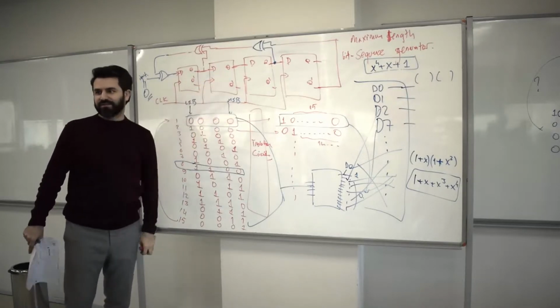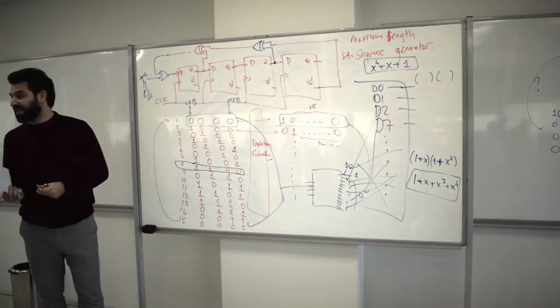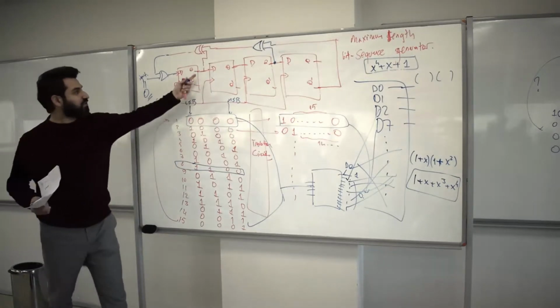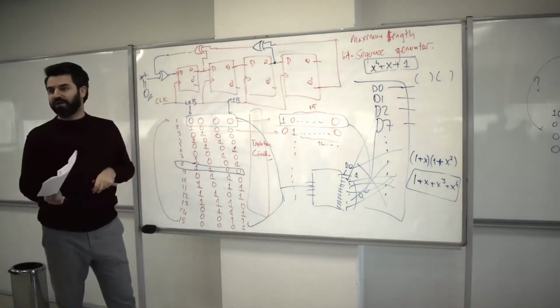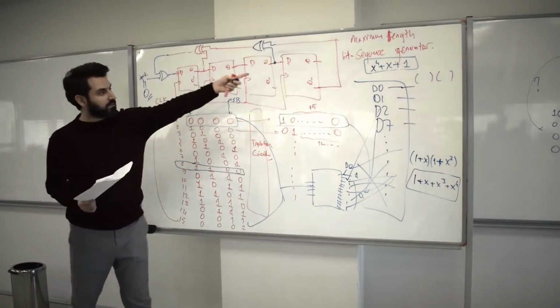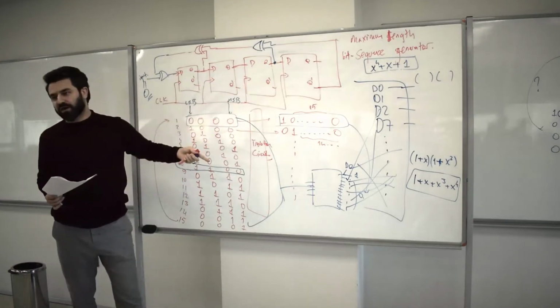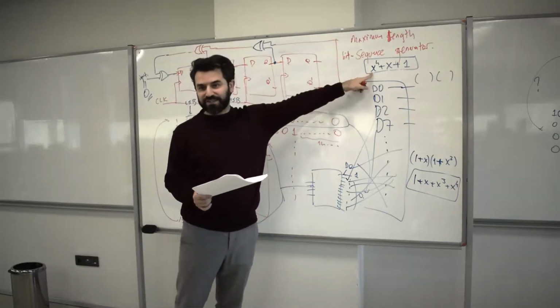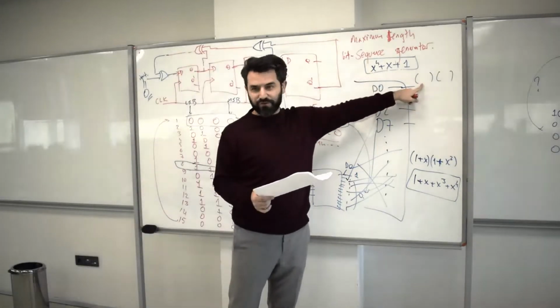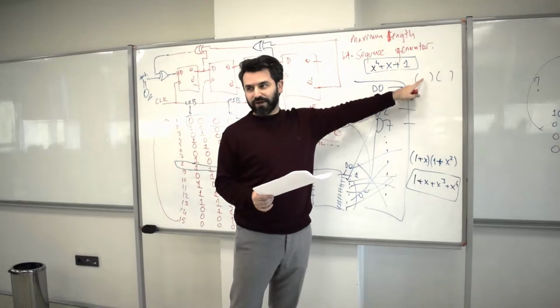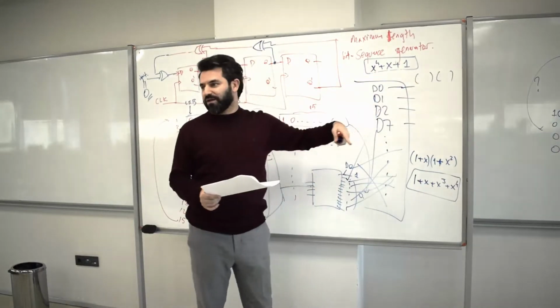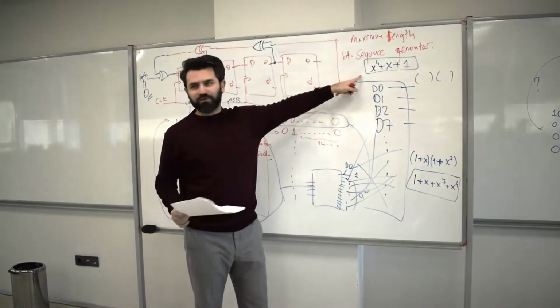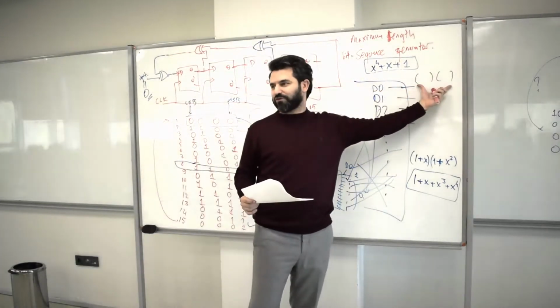Okay. So therefore, now you know the technique to check whether a given shift register with all these XORs is going to generate the maximum length bit sequences or not. Because now you know that there's a polynomial representation, then you look for whether you can factor it or not. Of course, if this polynomial is very, very high degree, it's going to be really hard to see whether it's going to be factored or not, right?